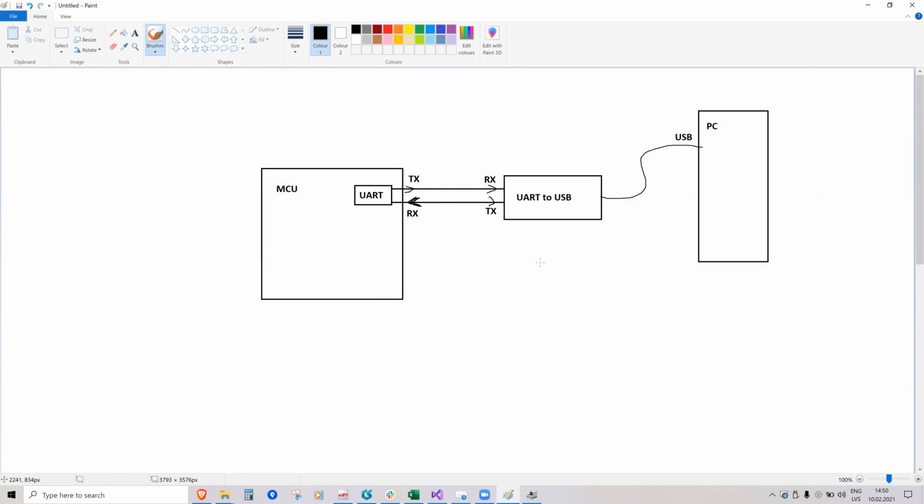But unfortunately, oftentimes many manufacturers of some devices actually write the wrong text here. Oftentimes on their devices, instead of RX, which is the receiving end, they would write TX, so that you would connect TX of the other device. And on the TX side, oops, I wrote the arrow in the wrong direction.